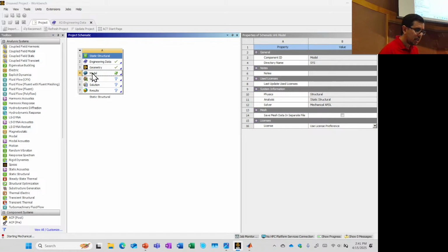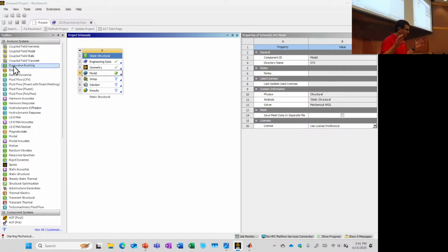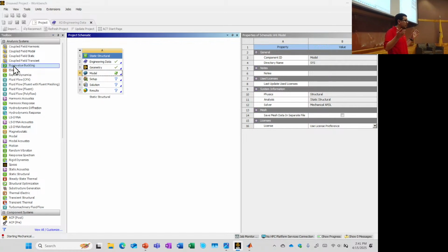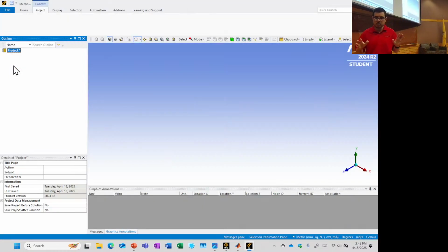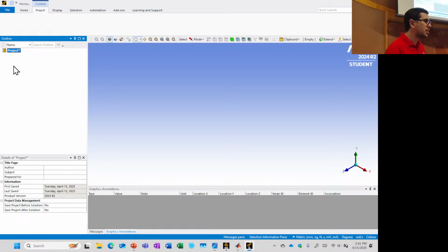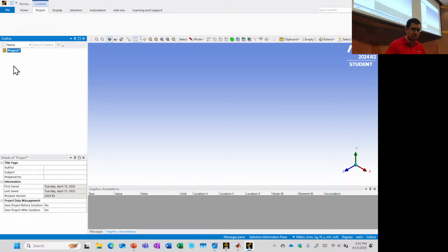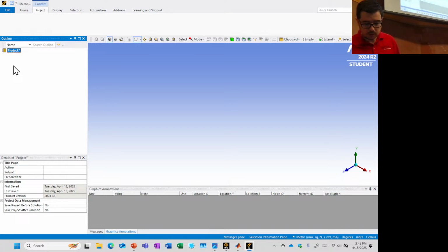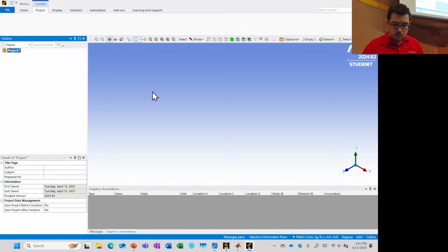And the first thing, before, you'll see that there's this eigenvalue buckling. That's what we're going to use in a little bit. But first we're just going to put the load in compression. Until we enable the buckling, ANSYS doesn't care about the possibility of buckling. It's just going to calculate the stress through the structure. So we're waiting and should have enough battery power.